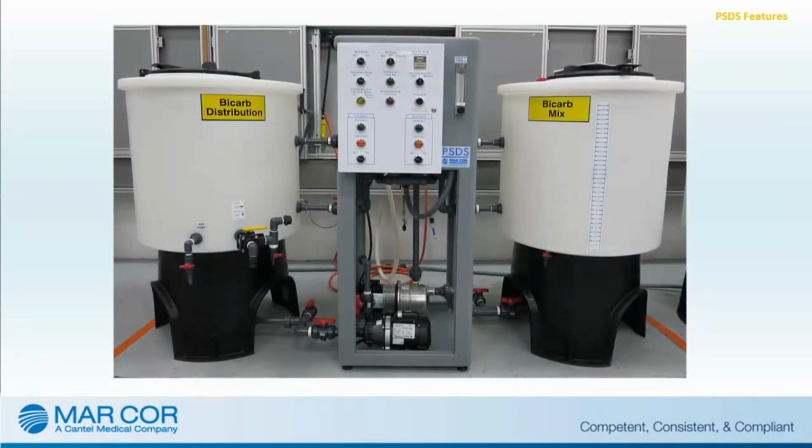Features of the PSDS include a large 3/4 horsepower single-stage centrifugal mix pump that provides quick and thorough bicarb mixing, a polyethylene frame that eliminates corrosion, semi-automatic controls that allow ease of mixed tank fill, an enclosed tank system that prevents contamination, separate 100-gallon mix and distribution tanks that permit large multiple batch capability, the capability to mix an additional batch of bicarb solution during patient treatments without interruption,